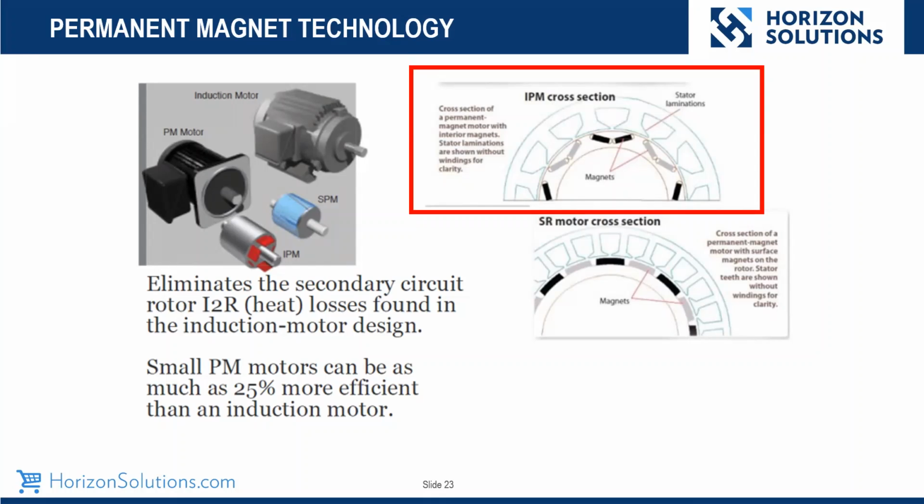We also have a list in the back of our manuals, in the 750 manual, that gives you some great suggestions for permanent magnet motors. It's in one of the appendices. But basically, when you've got a permanent magnet motor, you've got magnets inside, like Kevin talked about, that were the magnets on the laminations on the induction motor. Now we're going to mount these magnets inside the motor and use them for the attraction. These are usually a permanent magnet motor technology. They're limited in size, but they give you great instantaneous torque, and they give you really good efficiency.